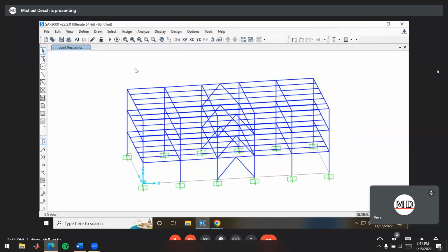Okay. So before we're done with the geometry, we have one more thing we need to do to handle the geometric modeling of all of our frame elements. If you remember, it said basically everything is connected with shear connections and then some of them are connected with moment connections. So this is based off of how we generally model structural connections when we're doing structural engineering.